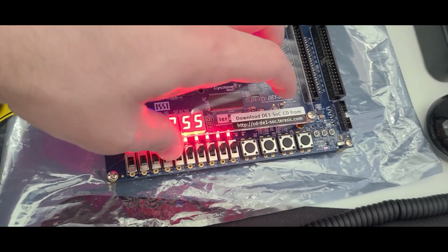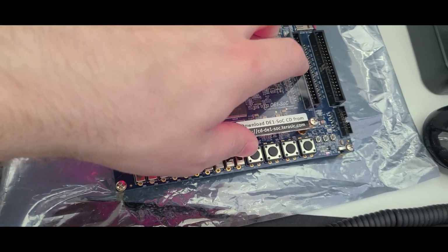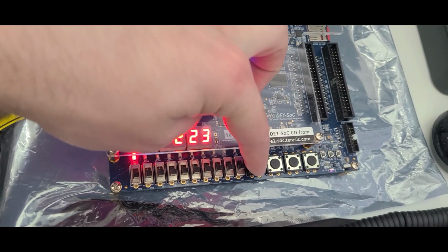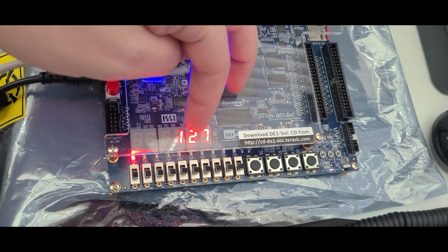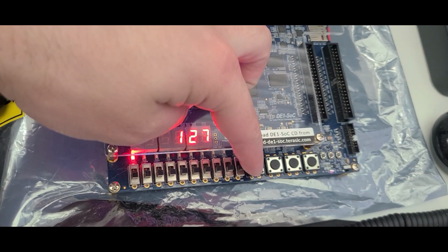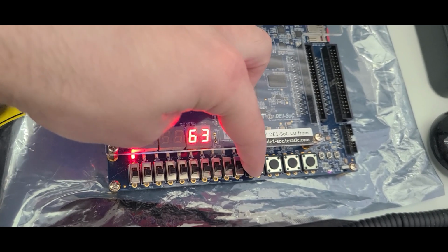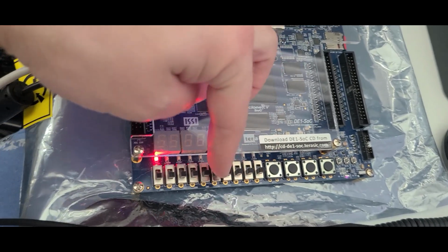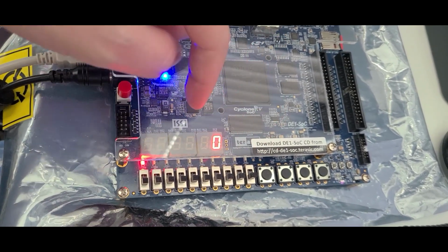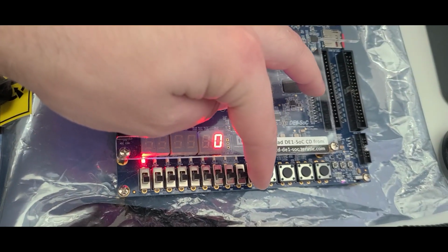And then let's set this back down to 0. So after 4 times, this should go down to 128. 127. Close enough. And then let me hit that 4 more times. And if you actually do the math on that, yes, it should go to 127 because it's truncating, and it's not going to round up.